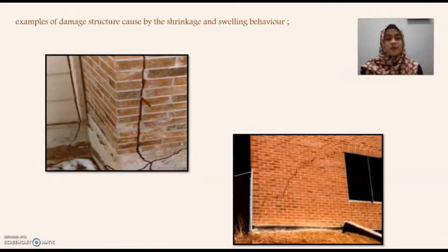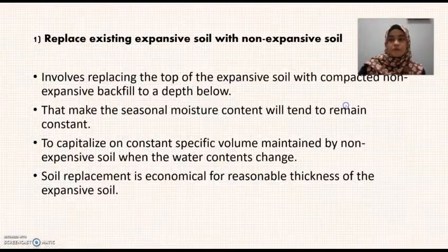And these are a few examples of damaged structure caused by the shrinkage and swelling behavior. As you can see from the two pictures here, there are cracks in the structure of the building due to the shrinkage and swelling behavior created by the expansive soil.